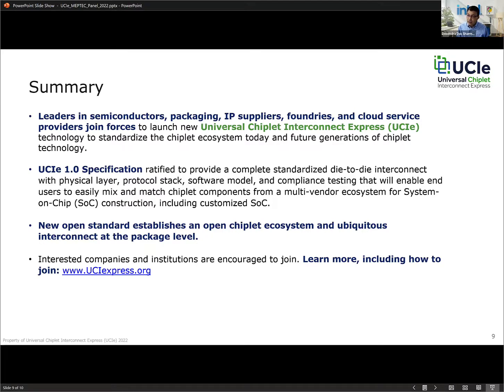On the other issue of memory, as you saw, we have CXL.memory. So you can definitely put the memory controller on the other side and have memory attached to that. I believe the question was, and it's a philosophical question, and we are also still discussing that in the consortium, about the memory controller moving away from the CPU to closer to the memory die. In other words, you have a separate memory controller die that's controlling the type of memory that you have. That gives us flexibility, and you're basically independent of the memory technology, so to speak.